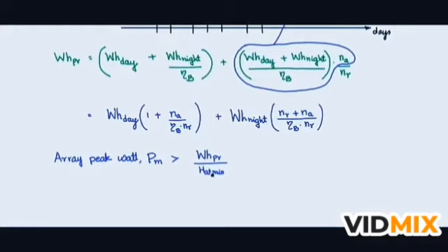So for Bangalore, we found out that it was around 4.58 kilowatt hours per meter square per day. So WHPV by H hat minimum, and here this H hat minimum is having the units of hours and not kilowatt hours per meter square per day, because we are numerically using the value of H hat minimum to represent so many hours of 1 kilowatt per meter square radiation, standard insolation. So H hat minimum here will numerically be same as the hours of equivalent standard insolation.